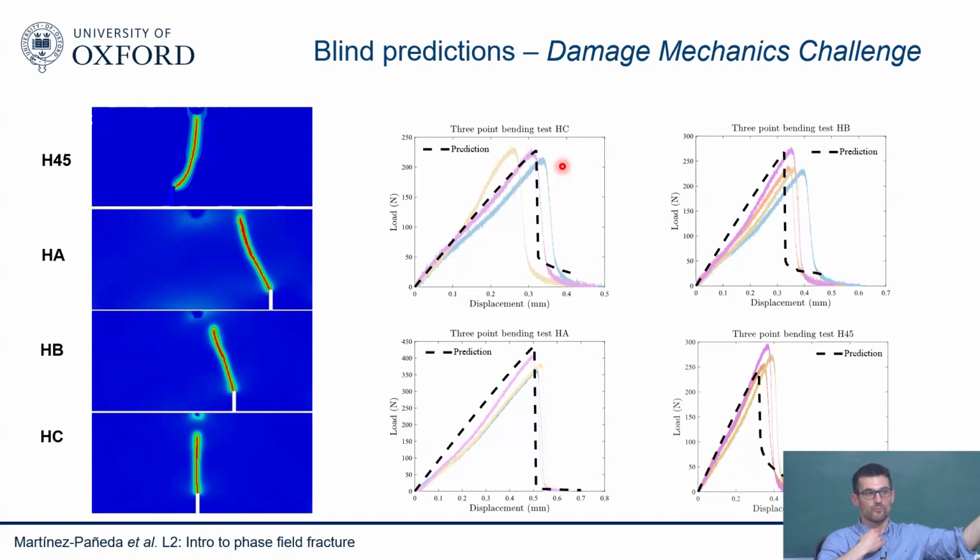So we would have to extrapolate from our toughness and strength to the porosity influence on toughness and strength. Since they gave us one and printed all with the same method, we could calibrate strength and toughness with one, and then predict the other ones. There could be a bit of anisotropy effects. Nothing is perfect, but for the time being, it seems that this kind of isotropic description does a good job. So the porosity will be embedded within the toughness and strength. I think that's the key takeaway.